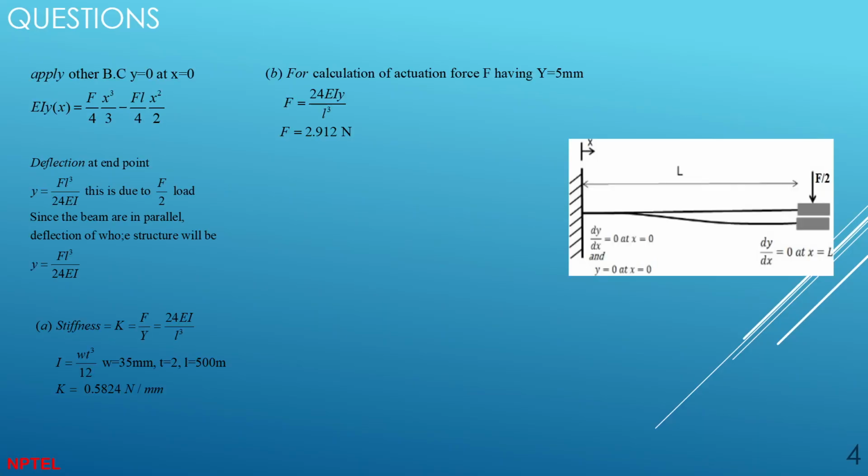They wanted to know, if the deflection is 1 micron, what will be the mass change. So y is equal to 1 micron, just put it there. It can measure up to 5.824 times 10 to the power minus 4. When you convert to millinewton, for 1 micron it can measure 0.5824 millinewton. This is how small your mass system can measure.